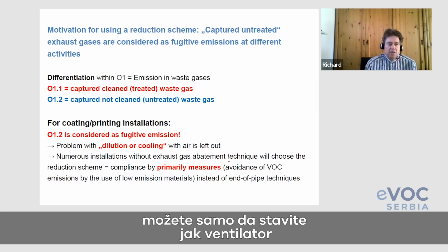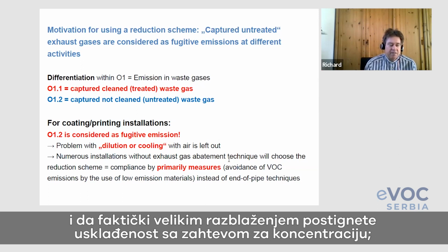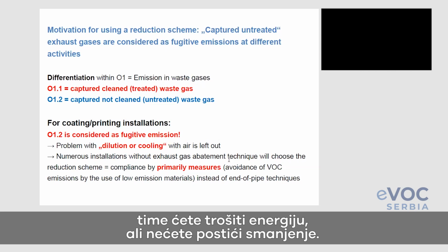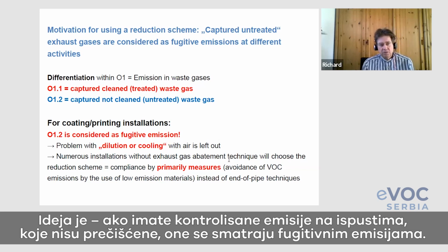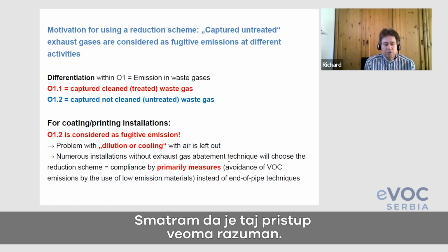You can just put on a very strong fan, and so by the high ventilation rate, you can do a high dilution. You will waste energy, but you do no reduction. You blow just your VOCs to the atmosphere in a higher dilution. So that is the idea that we say, if you have captured stack emissions that are not cleaned, we consider it as fugitive emissions. I think that approach is very reasonable.